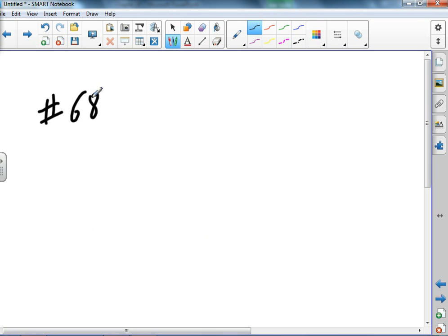We have a 3904 transistor. All right. The 3904 cannot be used in the circuit shown. Why? Consider the DC load line in the maximum rating shown. Well, it just says consider it, doesn't give you the answer. All right, so obviously we're violating something.